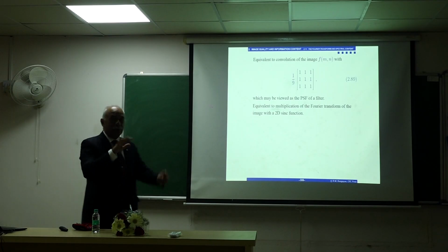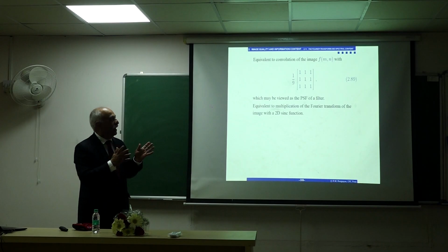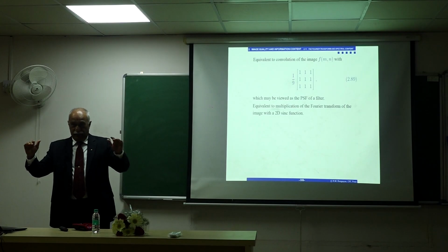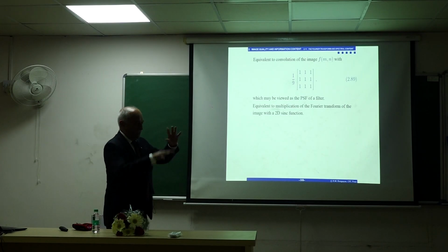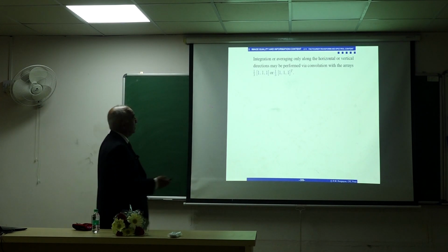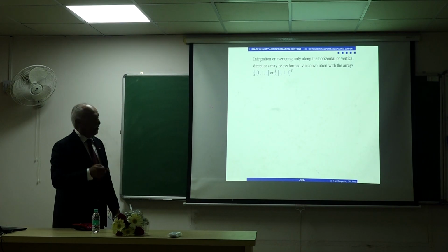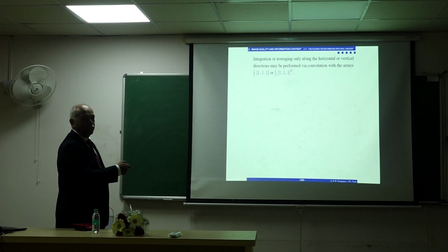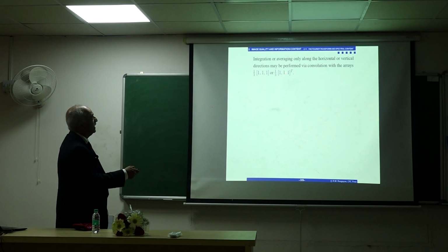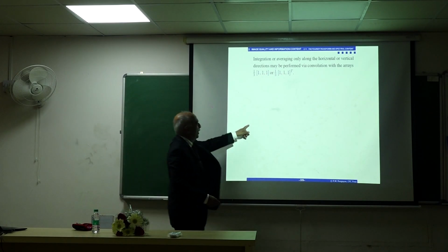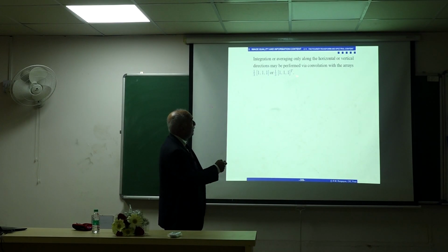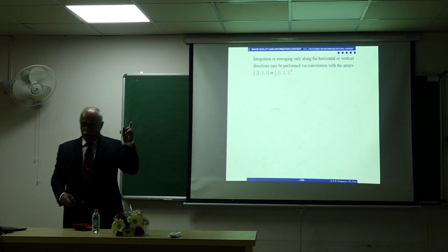It is commonly used, but it's not a nice low-pass filter in the sense that you want filters to have a continuous response in the frequency domain, smooth. But this is up and down, but we use this often. You can also do this in 1D, horizontally and vertically, by using only 3 pixels, either along a row or a column. If you want to write 1, 1, 1, to avoid interruption of the text, you write it as 1, 1, 1 and put a transpose. So T is a transpose. It's a column vector. So watch for that little T there.